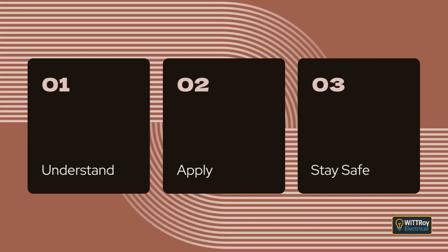Clause 3.12.3 Clearances. Clause 3.12.3.1 General. Aerial conductors must be installed with enough clearance from the ground, from buildings, and from structures. The clearances are set so the conductors stay safely out of reach under normal conditions and when they sag in hot weather. If the conductor will run hotter, or if extra sag is expected, more clearance must be added. When conductors end at a building or structure, the installation must prevent anyone from touching them accidentally.